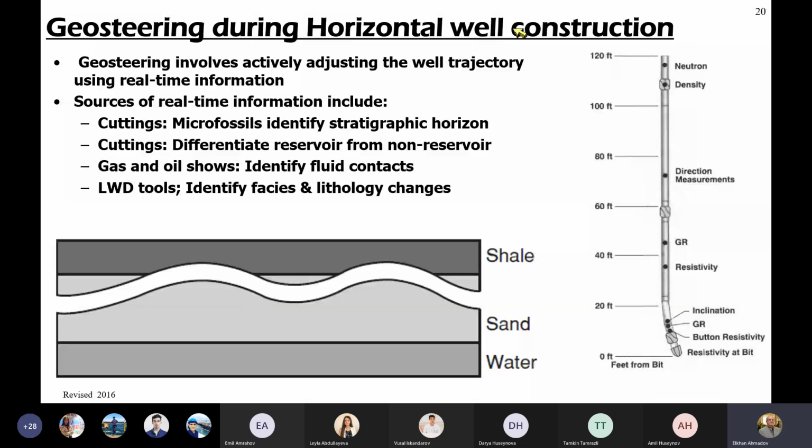Because, taking into account some possible lateral heterogeneity in the reservoir, if the water breaks through at any point of the wellbore, then unless it is a smart completion, where we can isolate zonal production or zonal inflow from each zone by packers and ICV, ICD devices, this whole wellbore will be damaged.